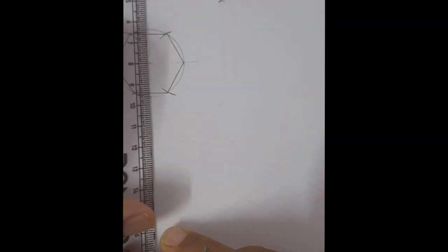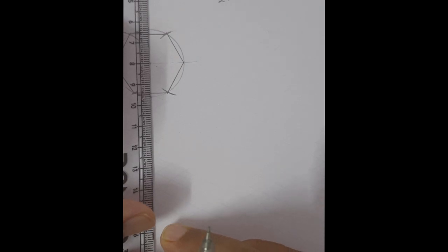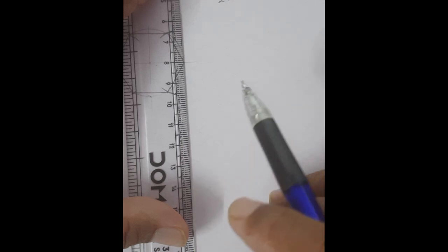So now you've got the center point of this hexagon. So you can measure with the help of a scale. So the distance you are getting is about 2 times the base edge in the horizontal direction. In the vertical direction, you need to check it. It is about more than the radius, about 14 mm on the top side and 14 mm on the down side. Okay. Or else you can just construct a rectangular block covering all corners of a hexagon.